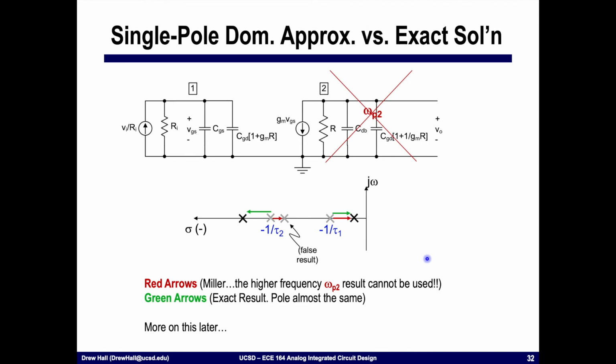And so let me revisit for just a minute this idea of the dominant pole and what's really happening to these non-dominant poles, and in particular, why we can't use the Miller's approximation. If we look at what's happening, there's an effect going on here in the circuit, and it's called pole splitting. Okay? Pole splitting is really that this CGD is bringing in the dominant pole P1, okay, and both techniques are correctly realizing that.